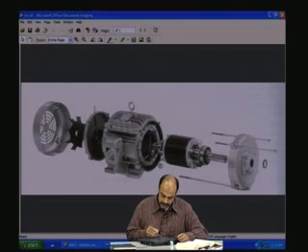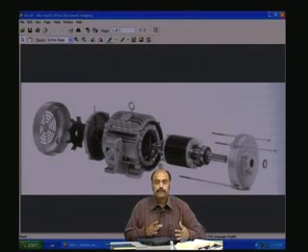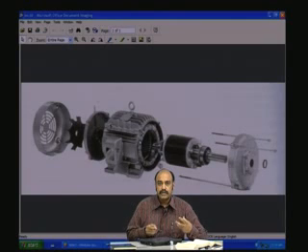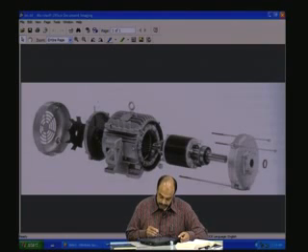So this whole coil is wound on the stationary system, this yoke, this is called the yoke, and that is the stator, that is anchored onto the ground through these foot plates, and that doesn't move. So that is why we say that once the poles are fixed in space, they don't rotate. And what makes the flux rotate is basically by virtue of the three-phase source that you supply, which are 120 degrees apart.